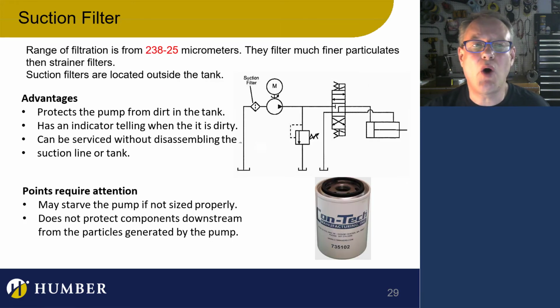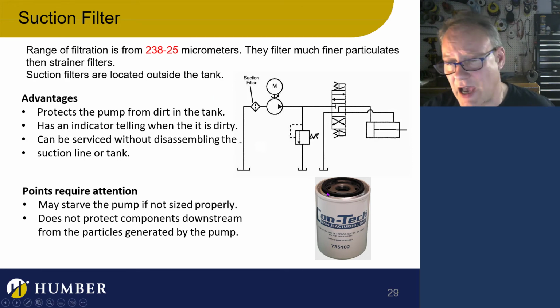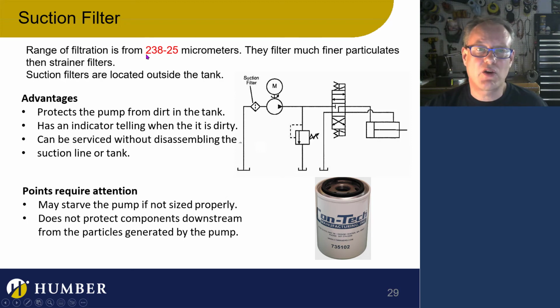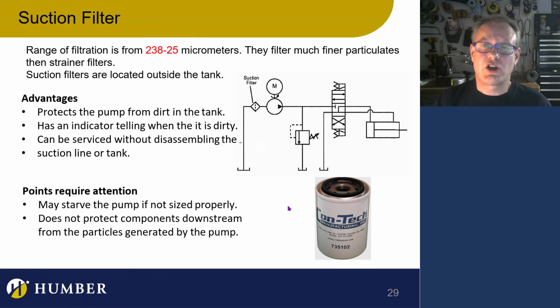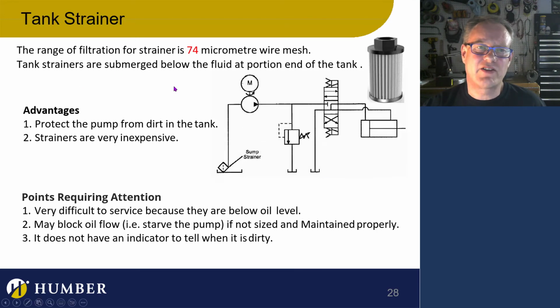But now as I go on to a suction filter that is an external suction filter, you're going to have this guy on the outside, and it is going to be better at getting more particulates. It's going to be external, and it's going to be a lot easier to clean. So essentially, what you're taking a look at here, this tank strainer itself, it's not filtering a lot of particulates.